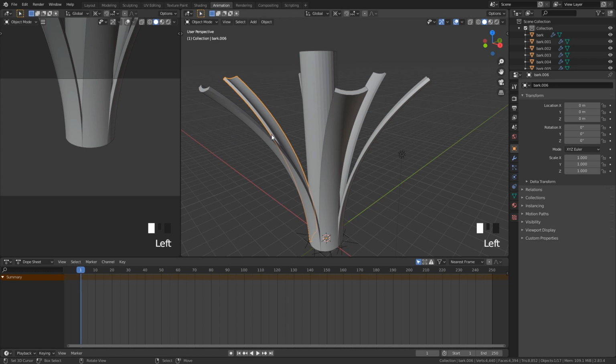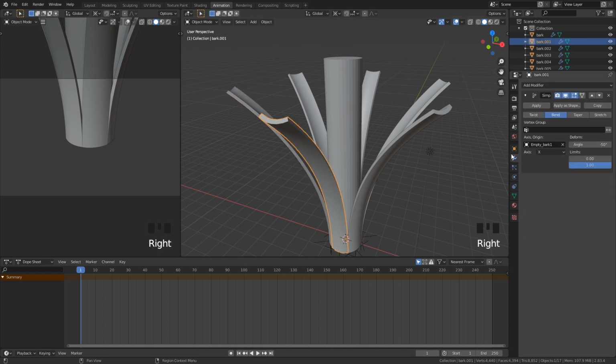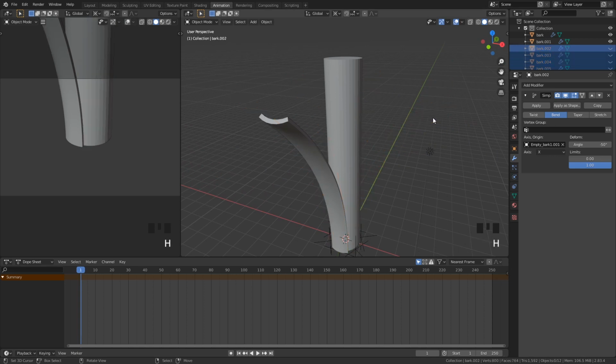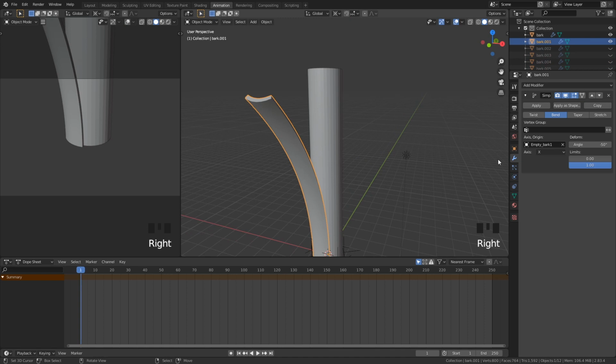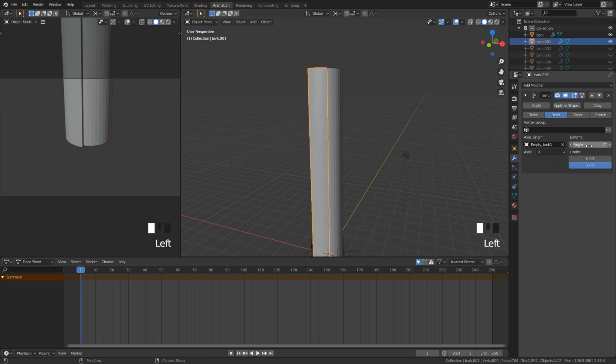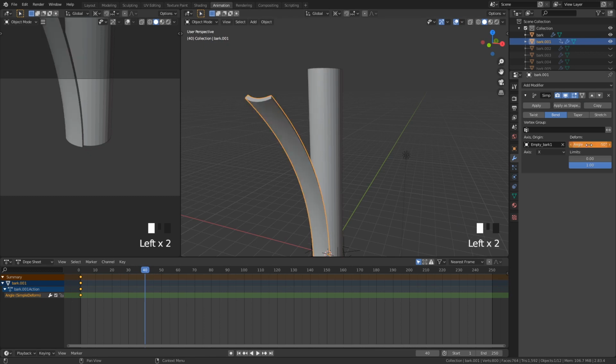So, I know a little trick though, and you only have to do one of these barks. Okay, so you can just hide all the other ones, just start with the one that is in the front view. So, we're going to select this, and we're going to make sure our angle is at 0, right click, insert keyframe. Then at around key 40, we're going to do -50, right click, insert keyframe.